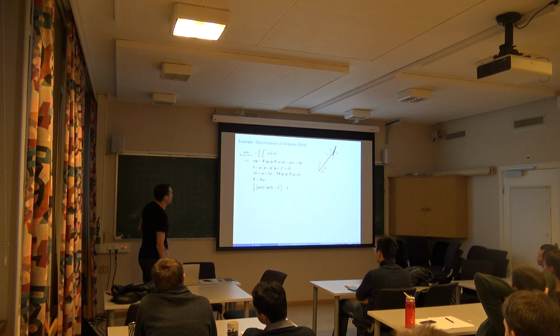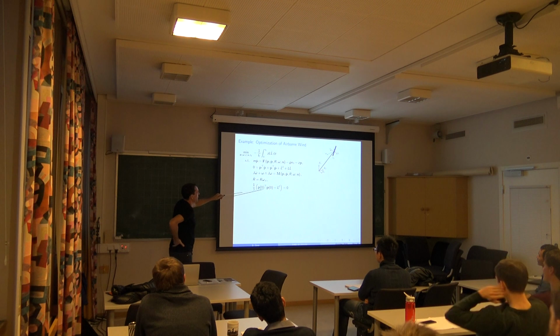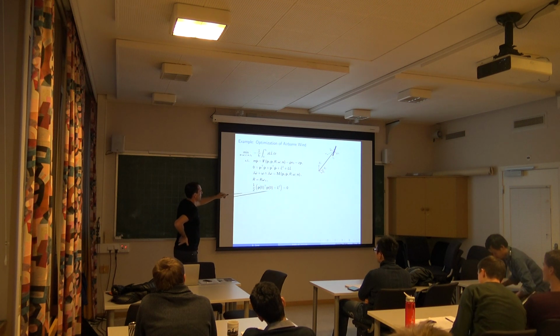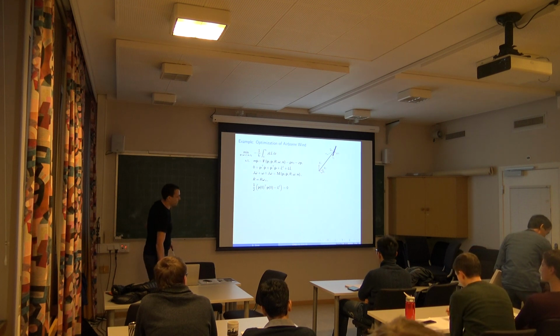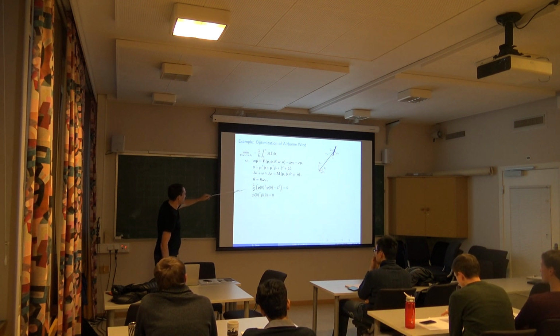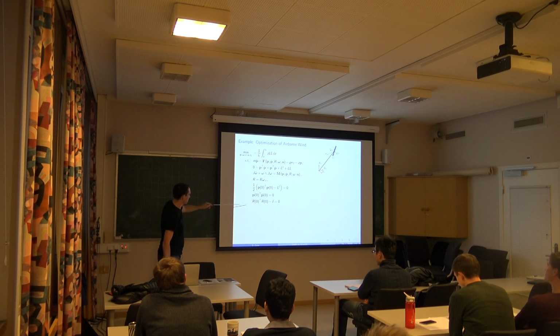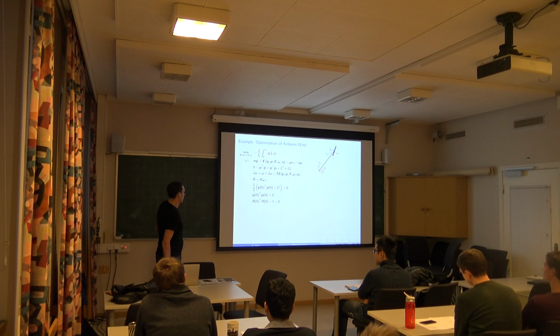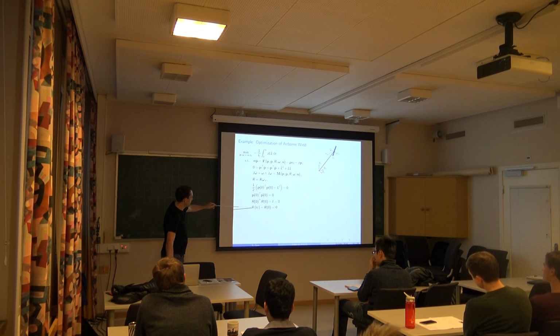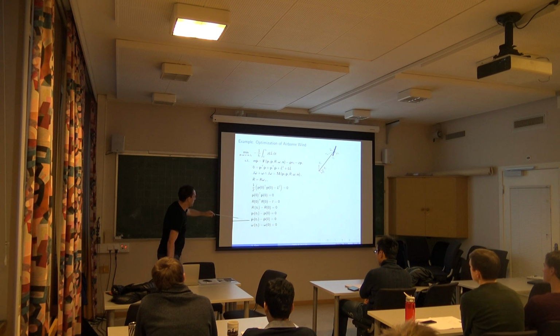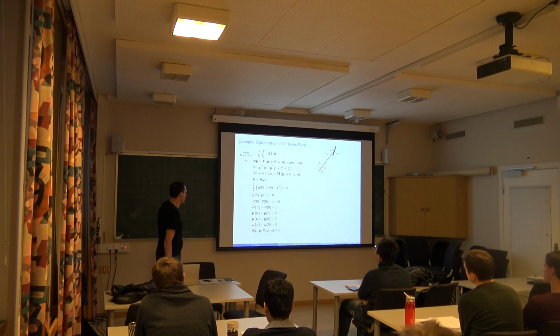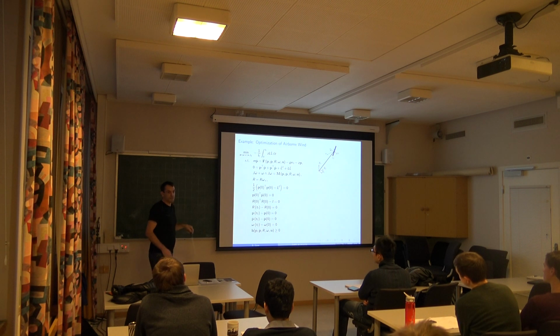But then you have to resolve these consistency conditions. You need to resolve that the UAV starts at distance L from the origin. You have this constraint. That's the consistency condition for the DAE form, index reduced. And then you have the consistency condition for the rotation matrix, and then periodicity for the rotation matrix, and then periodicity for the position, velocity, and angular velocity. And then you have some inequality constraints. So the OCP looks like this.